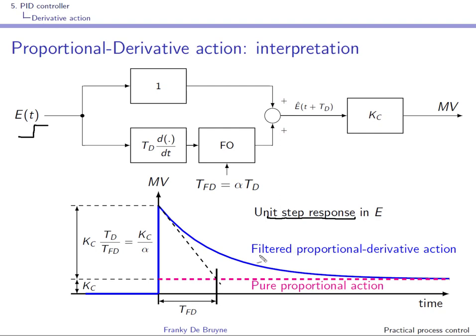If we have a process with a delay theta, at first the step response in closed loop with a proportional derivative action will look a lot like what you see over here. It is only after the delay theta that the response will start to deviate. So this part of the response will look different, but this part of the response will look very similar.